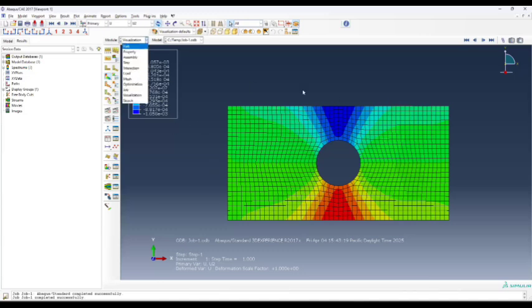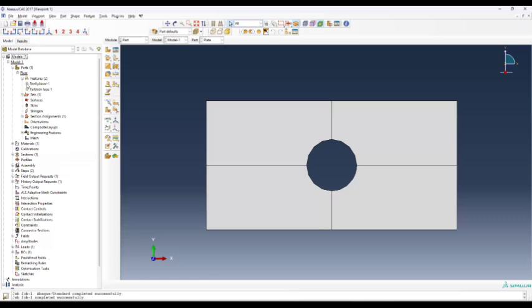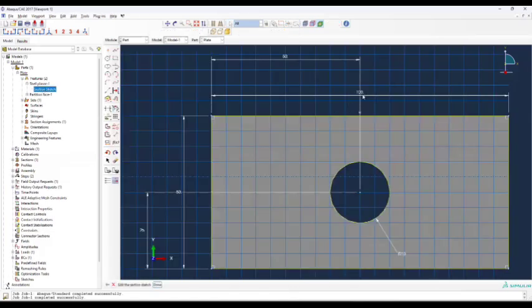Right. So, Jimmy, you have a question? Yeah, in terms of units, so when you dimension the lengths, those were in millimeters, right? No, I messed that up. So I put it as just a straight, like we can go back to our part. So here, shell planar. I did it as a meter; really, it should have been 100 times 10 to the minus 3. Right. But didn't it almost work out because you put your pressure in like 10 megapascals, so like millimeters and megapascals almost canceled out? No, I didn't split them, I did it all the way. So I did pascals. Okay. 10 with 6 zeros behind it. Okay. So the numerical values and the stresses are not meaningful to us, I guess. But this is just a demo, but yeah.